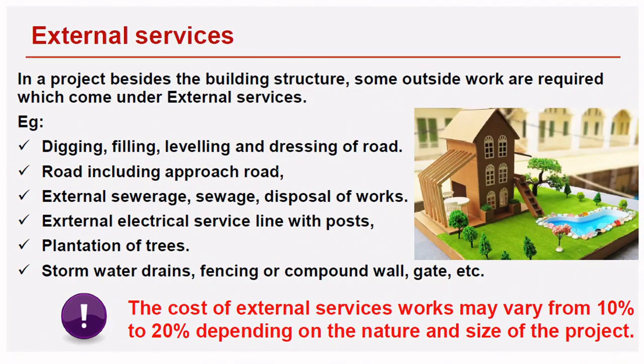Next is external services. What are external services? In a project, besides the building structure, some outside works are also required, which come under external services. What are they? Digging, filling, leveling, and dressing of road, including approach road, external sewerage, sewage disposal works, external electrical services, external electrical service line with posts, plantation of trees, stormwater drains, fencing and compound wall, gate, etc. So these are the external services.